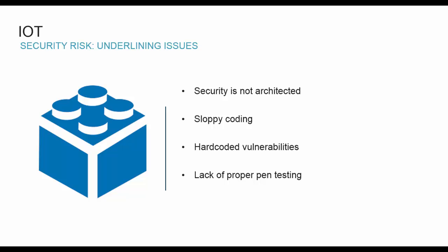The second issue is sloppy, inattentive coding, which is often caused by the pressure to release the product fast. This means the routing checks are being missed, memory allocation and flash reads are assumed to always succeed, the input data is assumed to always be verifiable, and the code to recover from errors is often marked as to-do and left for a later time. This makes it very easy to exploit vulnerabilities in the program just by triggering an error condition. At the least, by triggering that, the hacker will get a denial of service, and in the worst case they will have full control of the device.